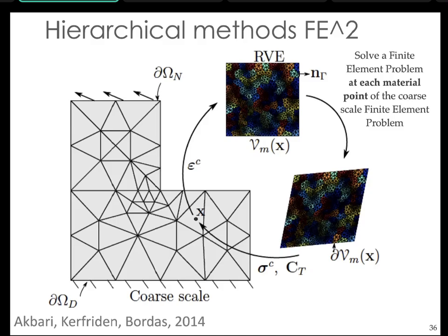We have a few papers with Timon exactly on this, and that shows you how to introduce cracks at the macroscopic scale using whatever happens at the microscopic scales. And I think you can take that idea and transfer it to other fields where these discontinuities happen. Now, the thing is, at each point here, you're going to have to solve an actual problem, because you're going to compute in the macroscopic problem, the coarse scale on the left, this L shape, a strain field, apply it on the representative volume element I introduced, then get a stress field and some sort of tangent stiffness matrix that gives you an idea of how the material is behaving at that point in time. And then you're going to pass that back to the point, compute the out of equilibrium forces, assemble all this in the internal forces, and then compute again.